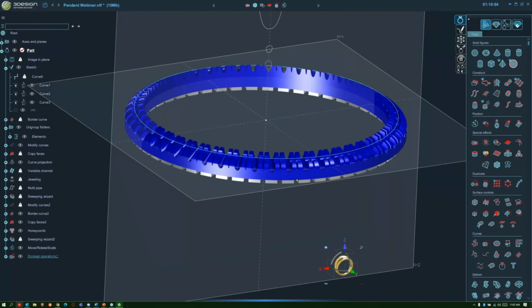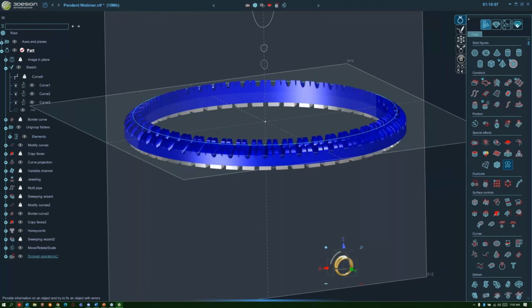For those of you who are new, that polygon conversion is the same as when you export an STL, taking your model and converting it. I find it's a nice way to quickly see if it converts to polygons. That means there are no bad edges. There's usually no problems there. If there were any, they would show up as bright red, as some of those black lines. So it's a good way to check as you're going instead of waiting until the end. It helps a lot with these troubleshooting steps.